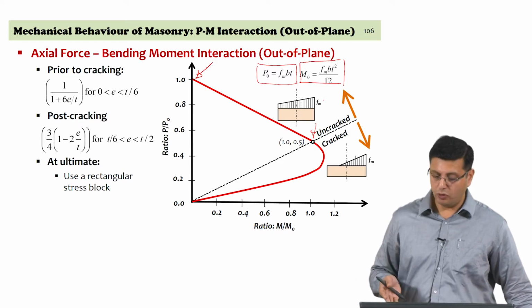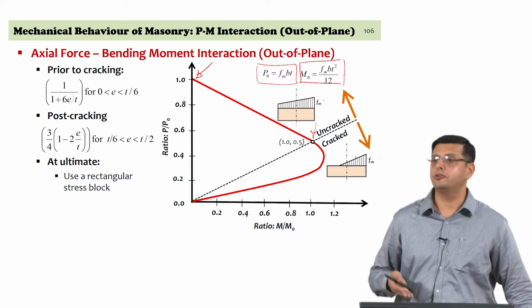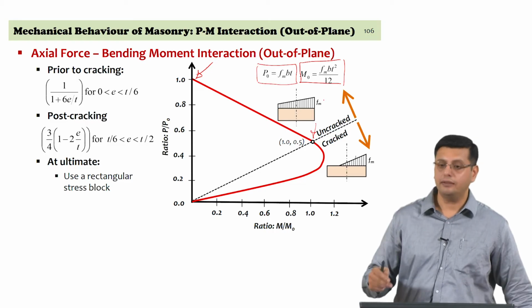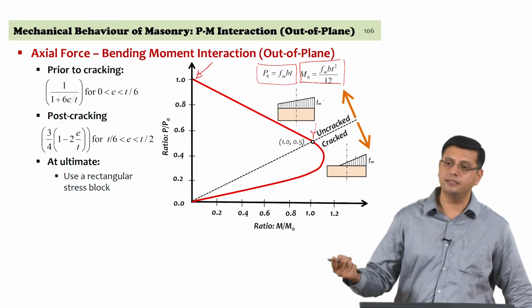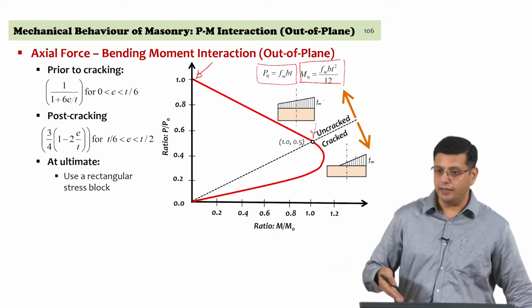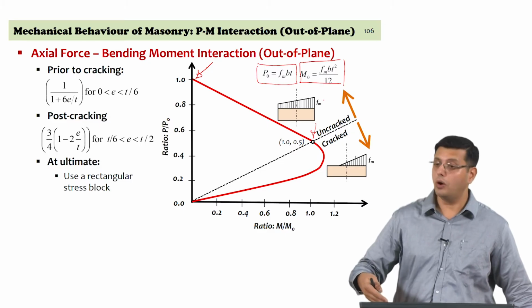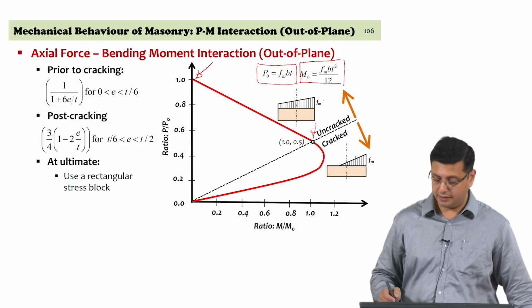Of course, here we have looked at an unreinforced masonry wall cross section. If you were to reinforce this wall cross section with 1 or 2 reinforcement bars, then you will agree that it is only in the cracked phase, once the steel bars start experiencing tension, that you will have improved moment capacity, which is in the lower half, in the lower 1/3 of the interaction surface itself.